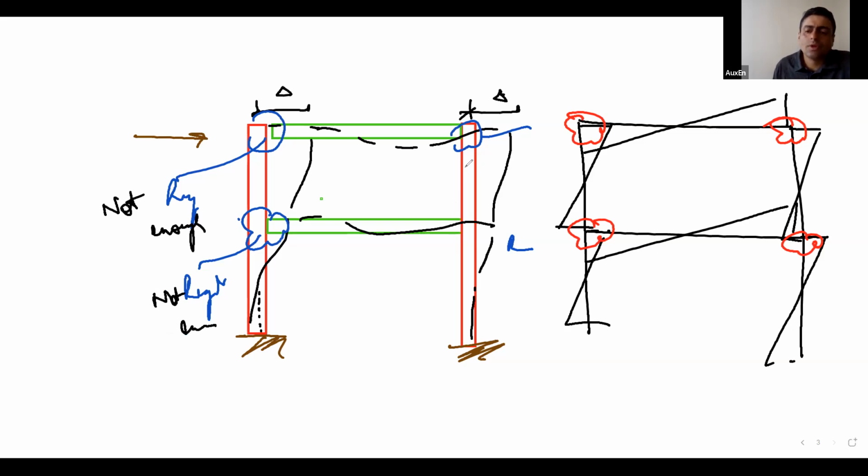So your design strategy was to provide a rigidly connected portal frame type of system to control the lateral sways. You did the modeling accordingly. Accordingly, you found out the member sizes. But when you went for the connection design and detailing, your connections were not rigid enough.